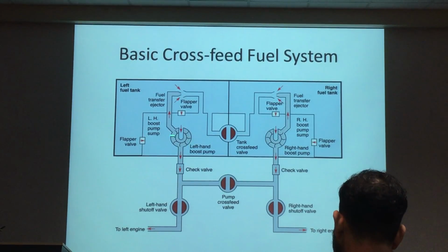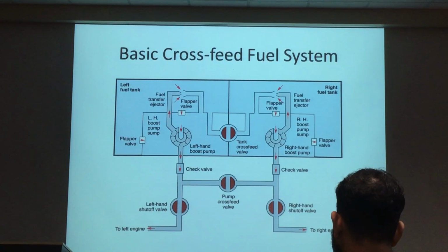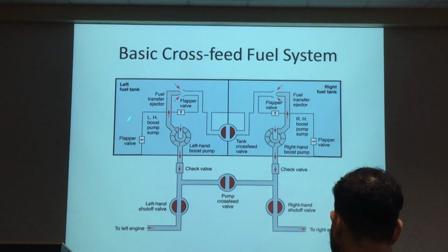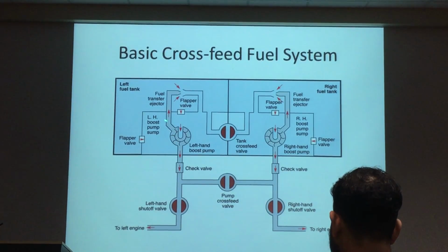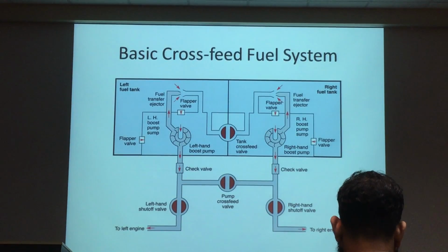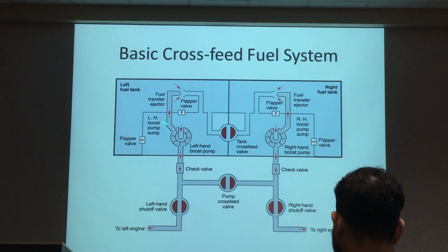The purpose is to make sure down here there is fuel, to make sure this pump is submerged in the fuel. Yeah? Okay, you pump it out. Remember, if something goes wrong, this pump fails, or this line is broken, the fuel is separated here, or fuel from another line comes in, so cannot. So you must have a way to isolate the tank. When the tank is isolated, the fuel remaining here becomes dead weight.